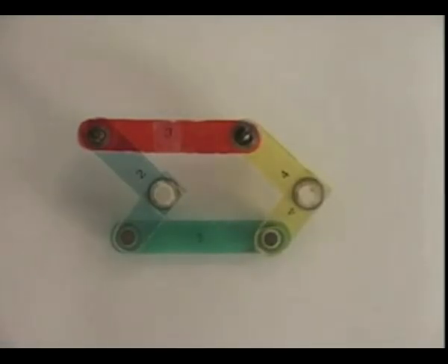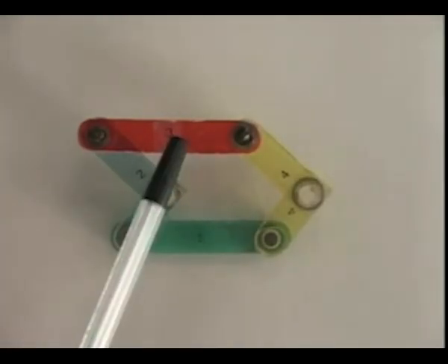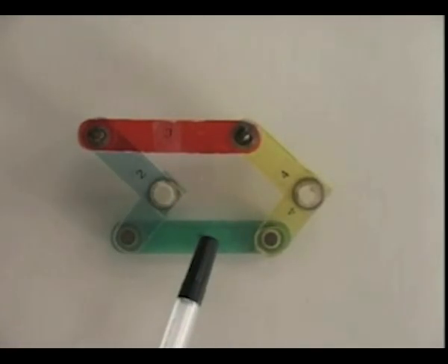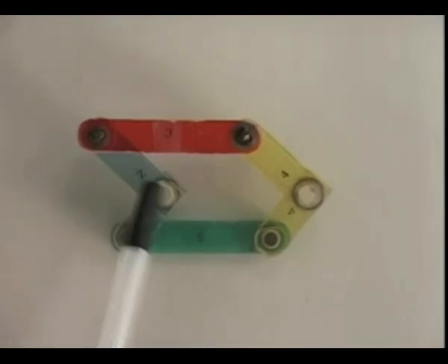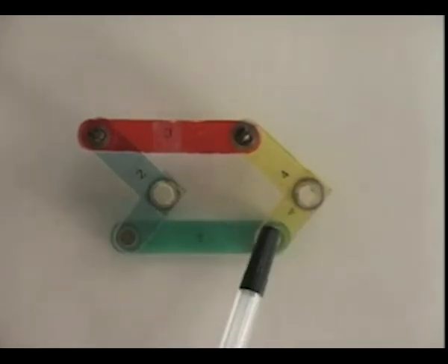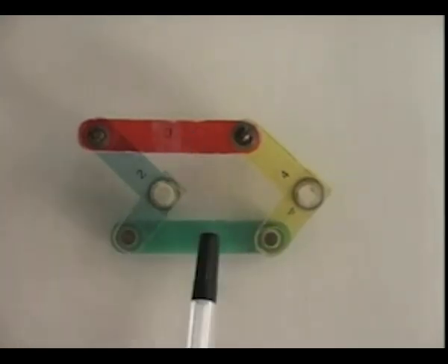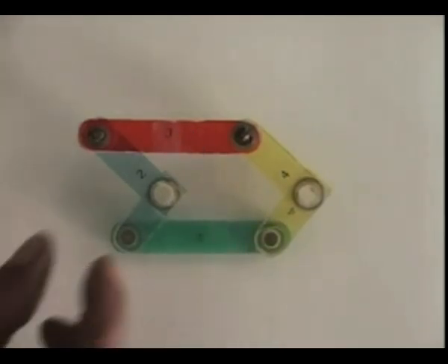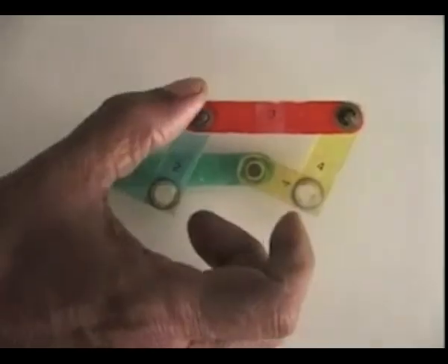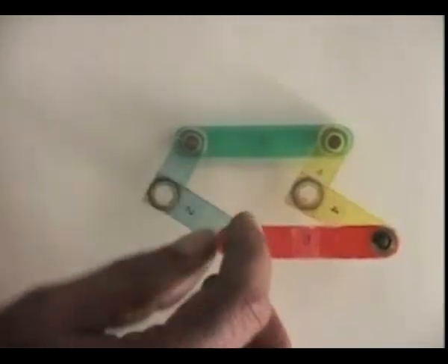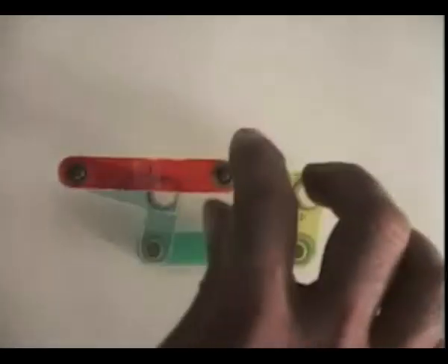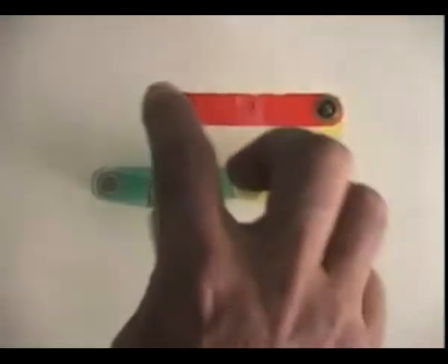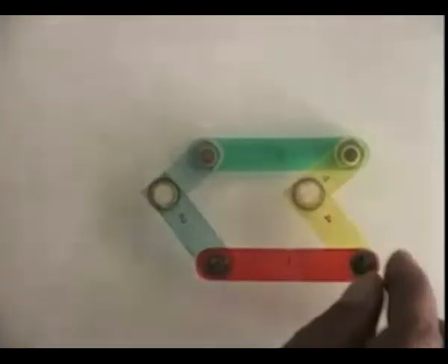Let us now look at the model of this parallelogram linkage with a redundant coupler. As we see, these two links are extended at 90 degrees and there are two parallel couplers. Consequently, here we should be able to maintain the parallelogram configuration throughout the cycle of motion. It can never flip back into anti-parallelogram configuration.